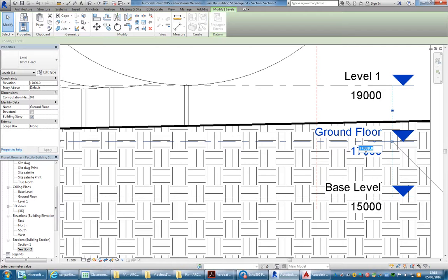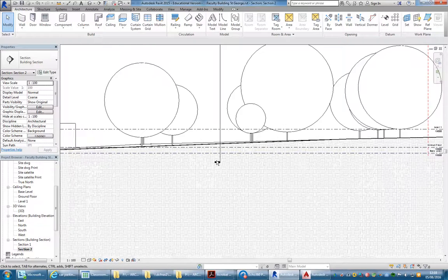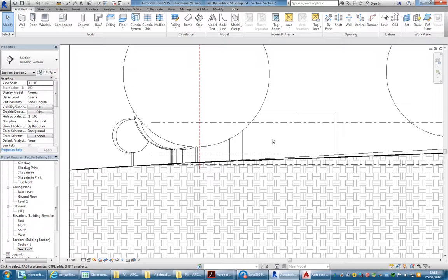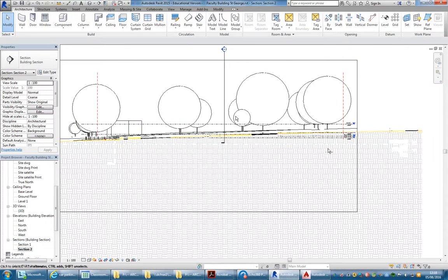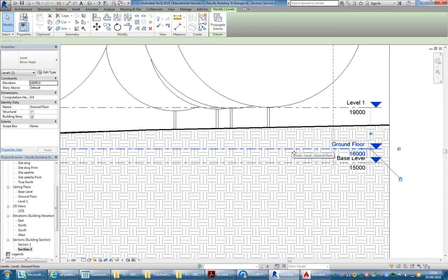And so I'm going to take mine down a little bit. So I'm going to make that 16,000. Okay, so I'm a metre above road level. Still need a few steps up, but that'll still work. So it can still change. The great thing about Revit is that if heights change, levels are easy to adjust, and if you set your model up properly, the objects will go with the levels, and the building should adjust itself fairly well.